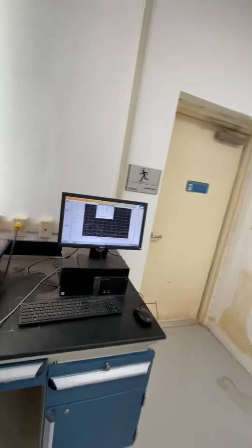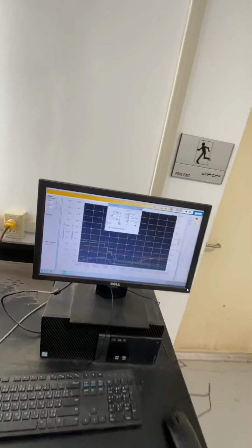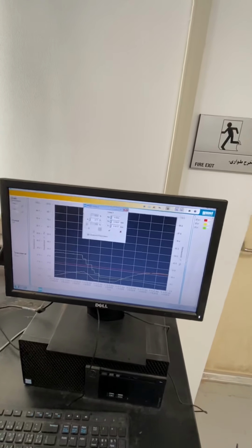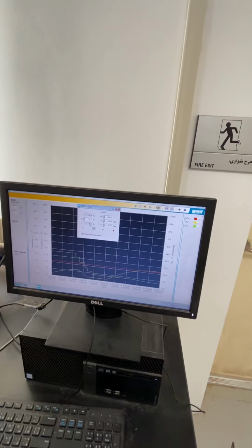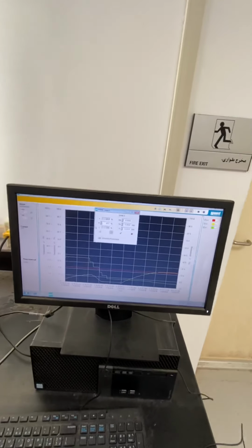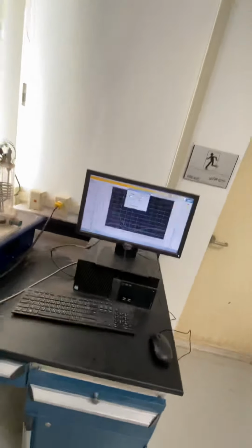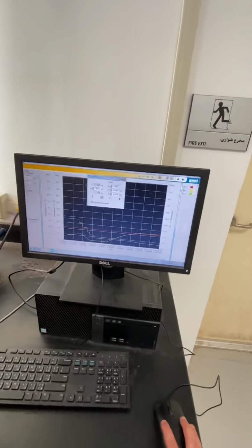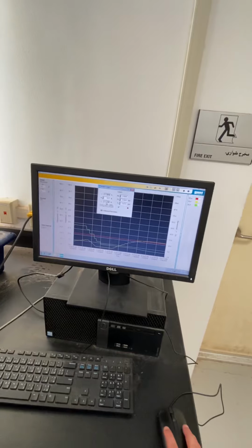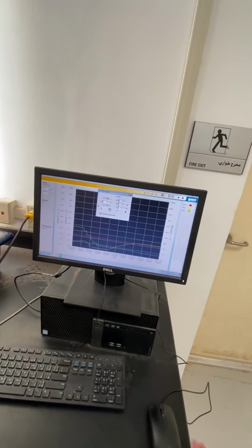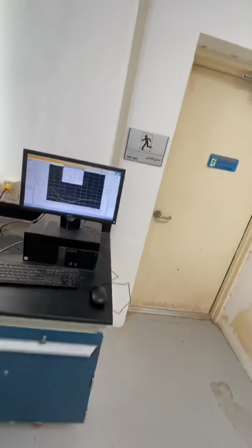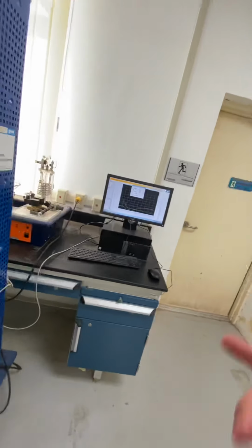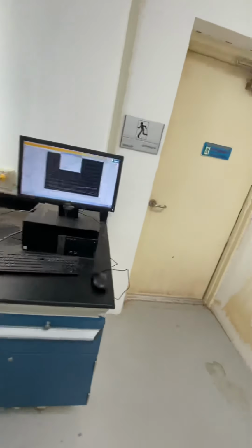Okay, you have been working for so long, and every time you notice that at 40% process value, the output signal is 10%. But after a couple of months, you notice that at the same process value, 40%, the output is not 10, it's now very close to 20. Okay, that will tell you right away that there is something wrong with the process.